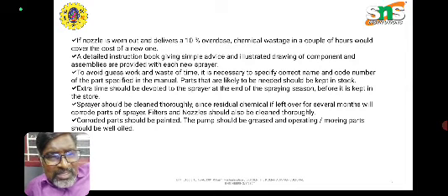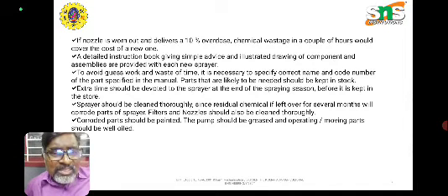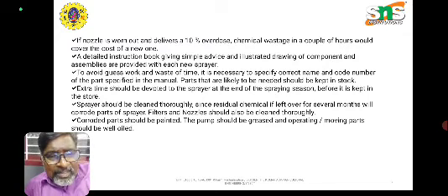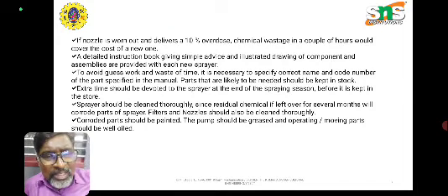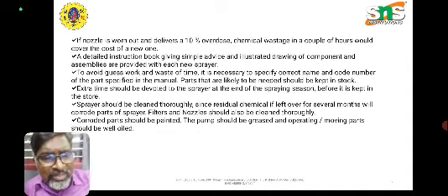So the filters as well as the nozzles should also be cleaned thoroughly. That means the small parts available in the sprayer are to be cleaned properly. Once the application is over, it should be cleaned properly, and if possible all the removable parts should be removed and kept separately, so that there is no chance for wear out as well as corrosion of the parts.